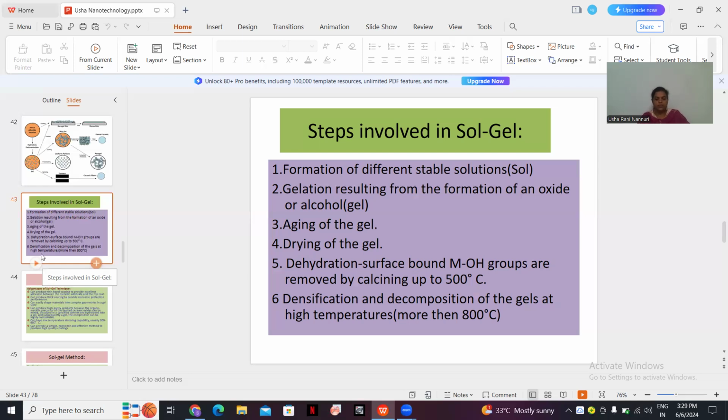The next process is condensation. Polymerization to form siloxane bonds occurs by either a water-producing or alcohol-producing condensation reaction. The end result of condensation is the formation of monomer, dimer, cyclic tetramer and higher order rings.